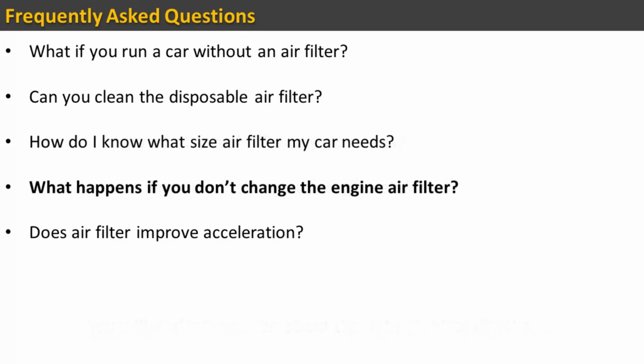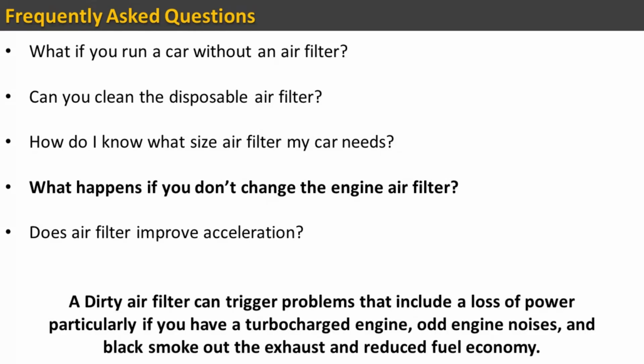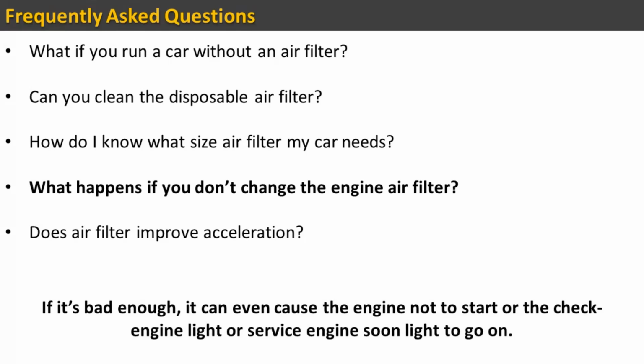What happens if you don't change the engine air filter? A dirty air filter can trigger problems that include a loss of power, odd engine noises, black smoke out the exhaust, and reduced fuel economy. If it's bad enough, it can even cause the engine not to start, or the check engine light or service engine soon light to go on.